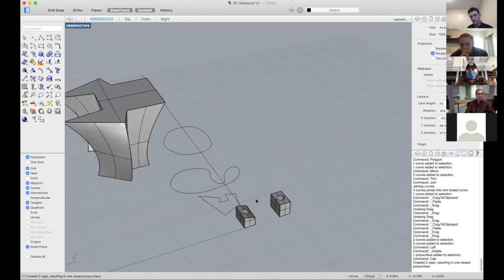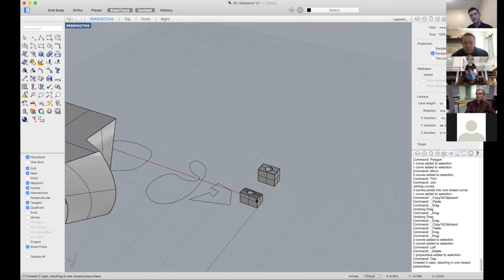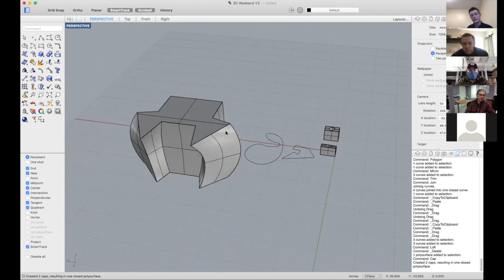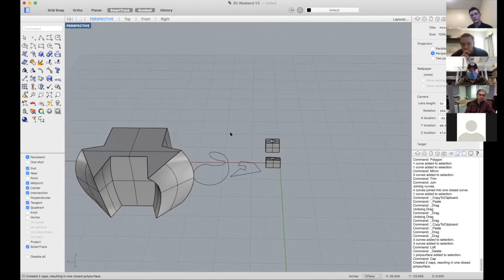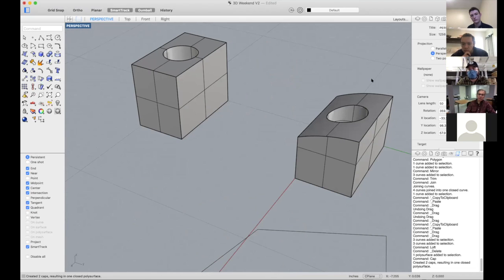A lot of people say that. I don't fully believe it. I think that Fusion is very good at doing organic shapes and things like that. And there are a lot of other options. The best way to do stuff like that is to create your profile, either sweep or loft a profile, and then start cutting away at it with different sections, and then rounding it out that way. Like I did over here, you can do this all over and get complex intersecting curves, but you're still constrained like you would be on a bandsaw, where you have your X, Y, and Z cut.